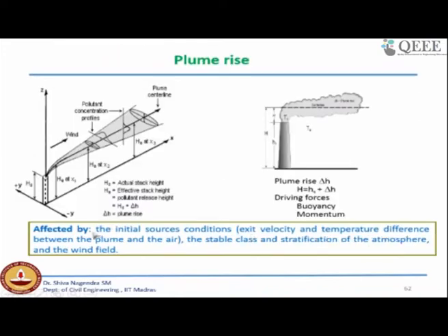Now you will come across something called plume rise, which I mentioned earlier. There are two forces that influence the plume rise: buoyancy and momentum. Depending on the temperature, you can notice the plume rise, and also if you have a fan to pump the emissions, that will also influence the plume rise.